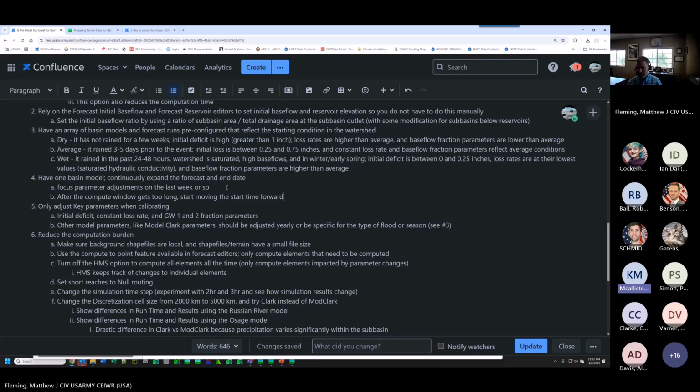Another thing that changed pretty significantly from the time the models were built was the additional linear reservoir, which is a much better baseflow method for pretty much all of our basins. My Rogue model wasn't calibrated with that, so I'm starting from a fresh calibration anyway with a whole new baseflow method.